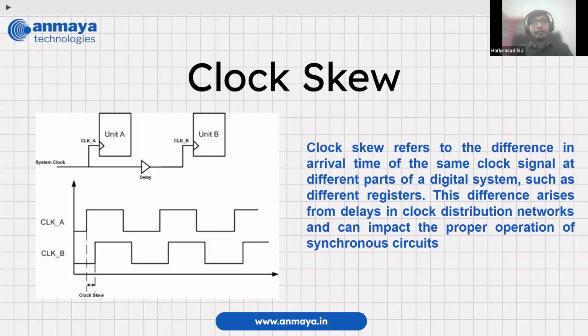Usually an external clock will be there, usually PLL or MMCM or TCXO. Especially for defense applications, we go for temperature compensated oscillator, oven compensated oscillator, OCXO we say, voltage compensated oscillator, VCXO we say. An external clock will be there.